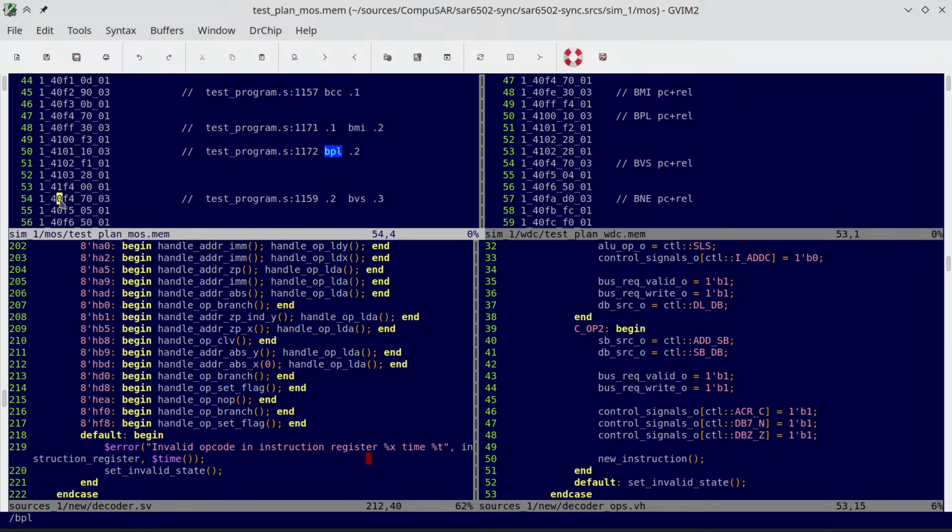And then we read from actually 40F4. Now this read from 41F4 annoyed people because this address is the next program counter in line. It's okay, it's kind of expected. It's under control. This address is unrelated to anything the program actually needs. So that was considered a bug in the CPU. As a result, the 65C02 fixed that.